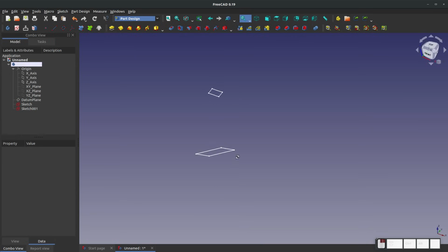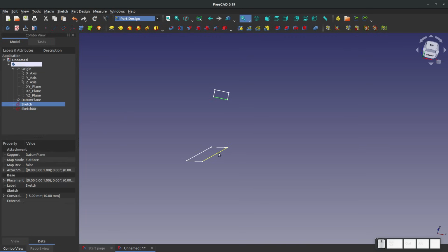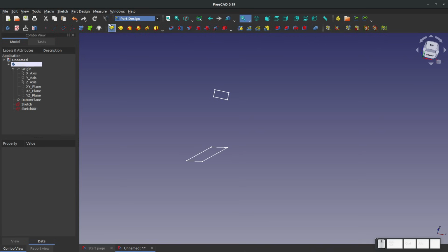So we have this tool called a loft, right? I sketched out a rectangle profile here, and I sketched out a kind of rhombus profile over here. And what if I want material to go from this rectangle to this rhombus, and in between slowly turn from a rectangle into a rhombus? Well, let's give it a try. This is called the Loft tool.